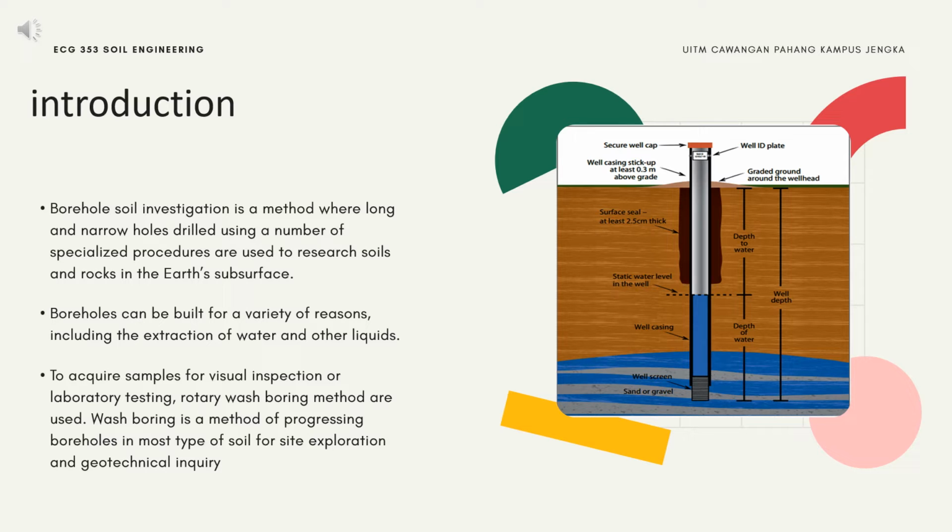Borehole soil investigation is a method where long and narrow holes drilled using a number of specialized procedures are used to research soil and rocks in the Earth's subsurface. Boreholes can be built for a variety of reasons, including the extraction of water and other liquids. To acquire samples for visual inspection or laboratory testing, the rotary wash boring method is used. Wash boring is a method of progressing boreholes in most types of soil for site exploration and geotechnical inquiry.